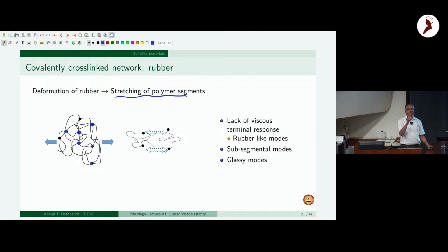On the other hand, when we are using rubber as an O-ring in an instrument where it's vibrating, or for vibration isolation, then we are taking recourse to its dissipative capacity to dissipate the mechanical energy associated with vibrations, so that it dissipates the energy and does not lead to transmission of energy from one solid body to another solid body.